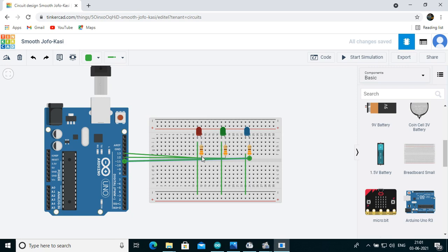Okay. So the LED light anode terminal is connected with the resistor, because the high current is supplying, so we don't want our LED to explode. That's why we connected the resistor. It will limit the current value, the current coming towards the LED, because the LED can only operate on a voltage of 5 volt or 3 volt, like that. Fine. And the current coming from the Arduino is a little high, so we need to stop it. That's why we are using the resistors.